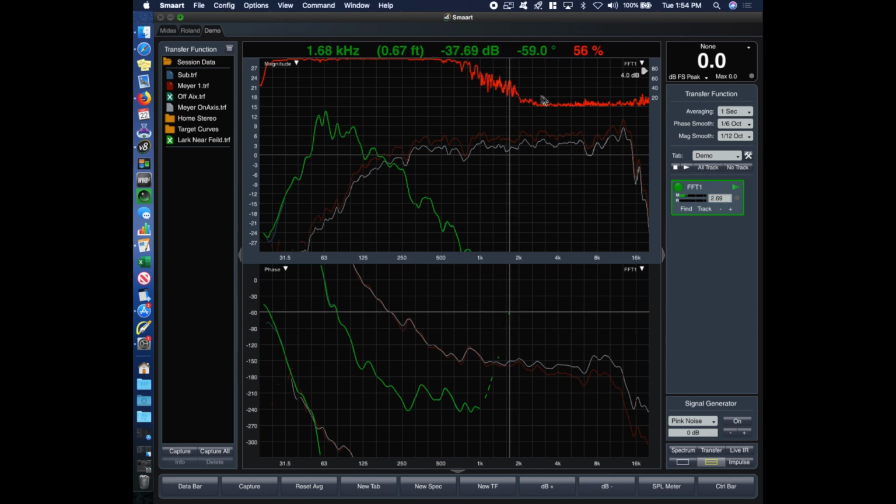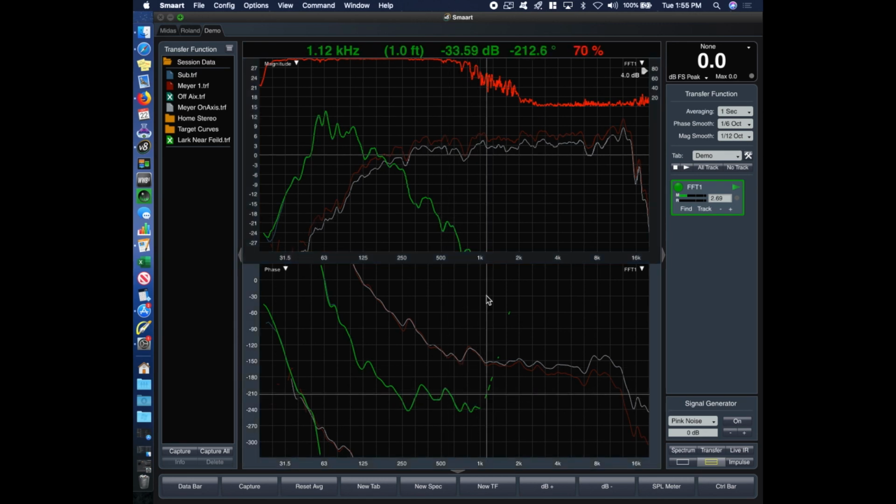And so do you guys see up here how low the phase coherence is after probably about 600 hertz or so? That's because there's such limited data within the content of this speaker. This is telling us that we can't trust anything that we see above 600 or 700 hertz. Make sense? So now we see the crossover that we have here, and we can tell that it's occurring roughly between probably about 120 or so down to about 275.